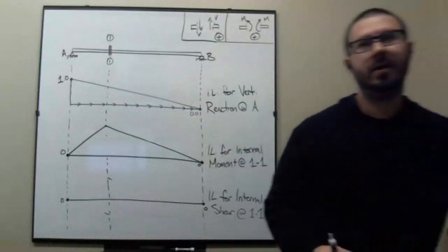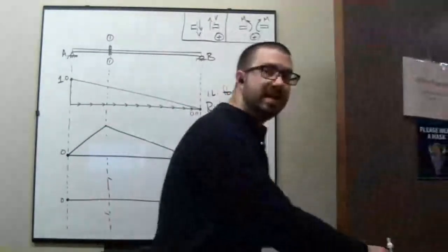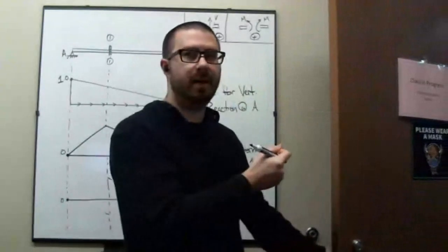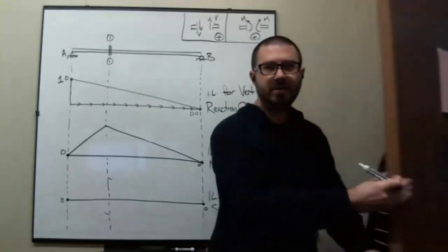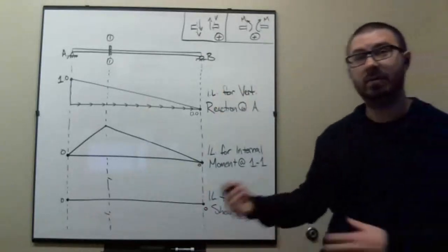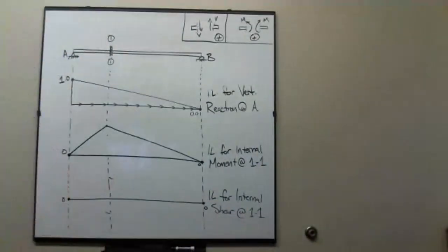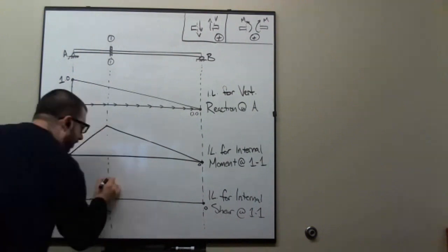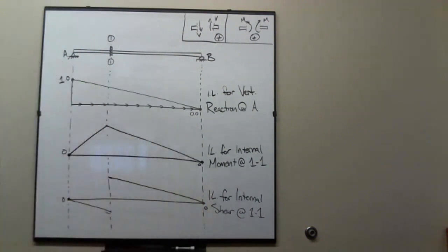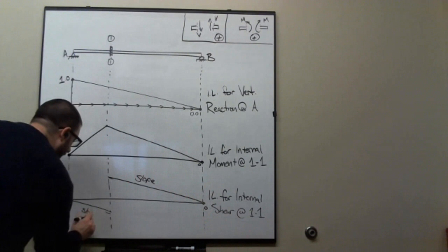You can still take a hinge section and shear on it. Like, here's my door, right? The door hinge freely allows rotation, but I can take this door and yank on it axially, and it still resists it. I can take it and shear it, and it's just fine. It's only the rotation that I'm releasing. Same thing with a shear release. I'm only releasing the shear, okay? Because I'm only releasing the shear, I'm not releasing the moment. So I have to draw this influence line in such a fashion that this line and this line both have the same slope. So this line has a slope, this line has a slope.